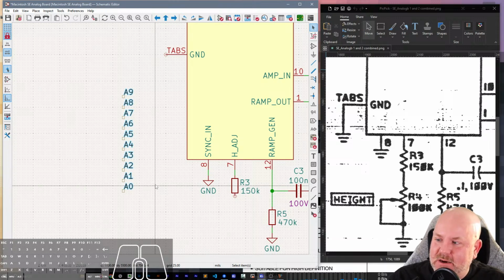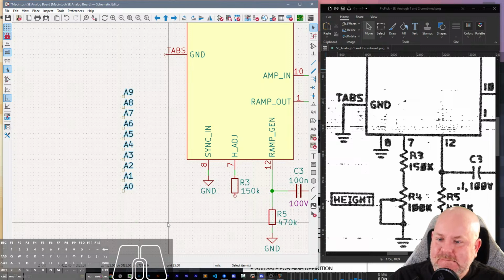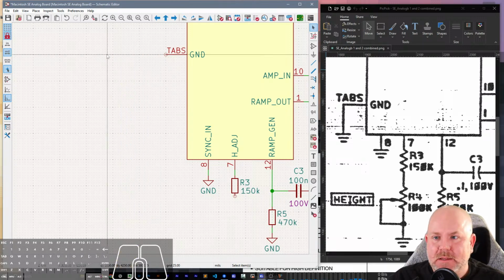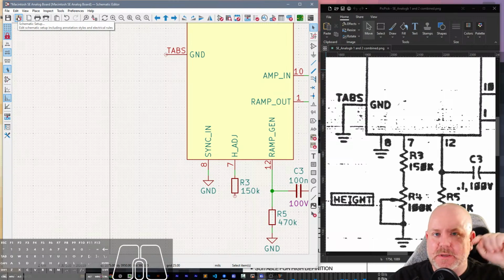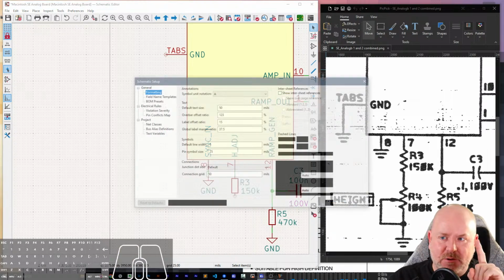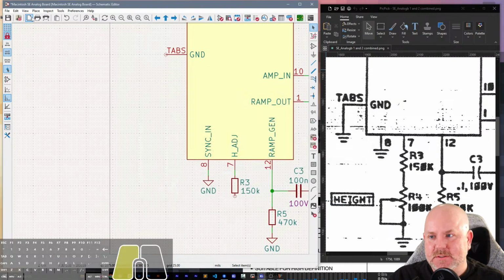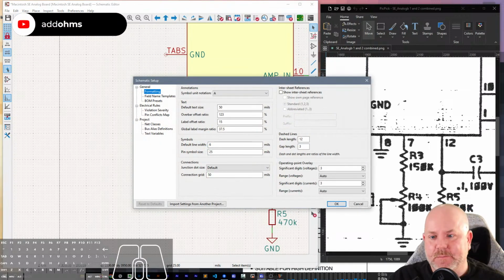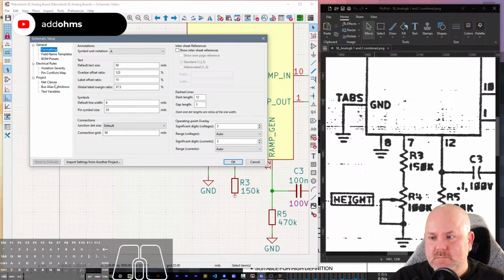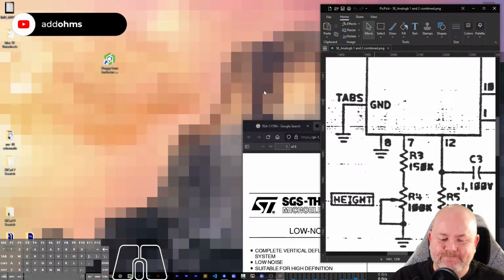Net classes, how to make these net classes in Schematic, and it's updated on the PCB side. So net classes are already synced between PCB and Schematic. However, the thing that gets missed is where it's at. So in Schematic, I'm going to go into Schematic setup, into net classes.